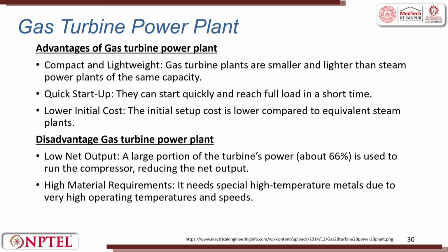What are the advantages? It is compact and lightweight, slightly bigger than the diesel. Gas turbine plants are smaller and lighter than steam power plants of the same capacity. Quick start, it is possible. They can start quickly and reach full load very fast. Lower initial cost as compared to the thermal power plant.